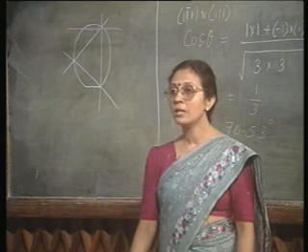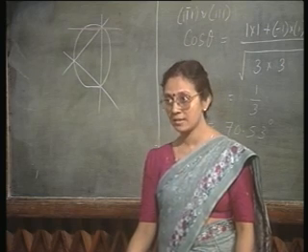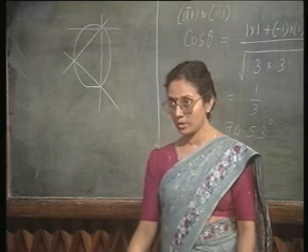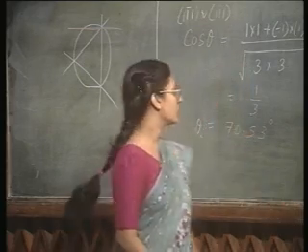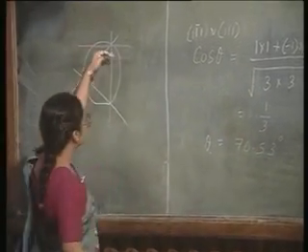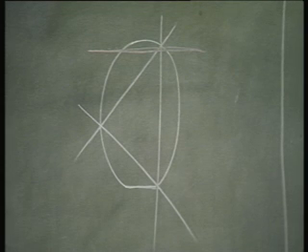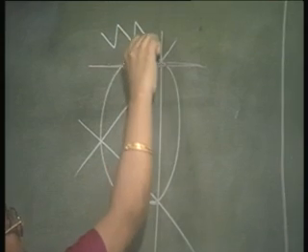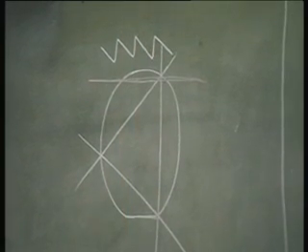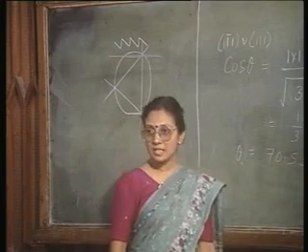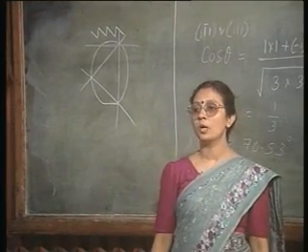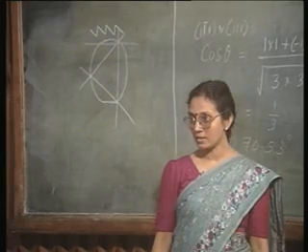So, it will resist, silicon will resist scribing along that line. Okay. So, what I will have is not a clean break along this line, instead I will have a zigzag cut with each zig and each zag along the 110 directions, right.